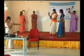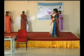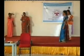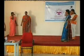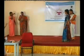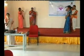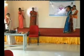Now when you see this person, she is standing near cell C, which means she is getting the power level from both the base stations, but comparatively a good power level from cell C. Whenever the signal level changes, the red saree person monitors the power level from both base stations. After monitoring, she associates with the best base station where she is getting the best power level. So she is getting associated with cell C. This procedure is called soft handoff.